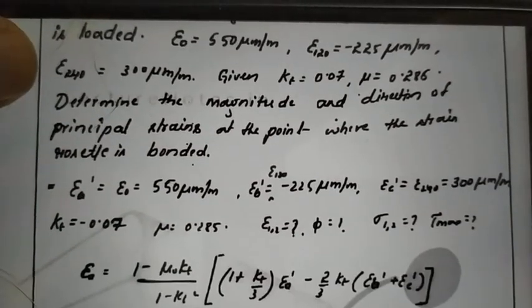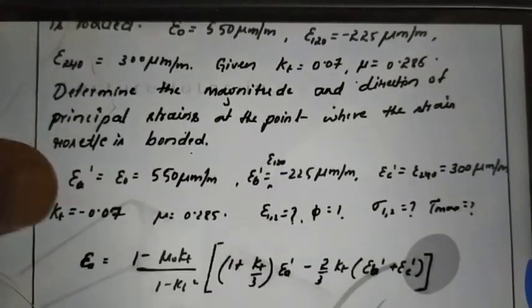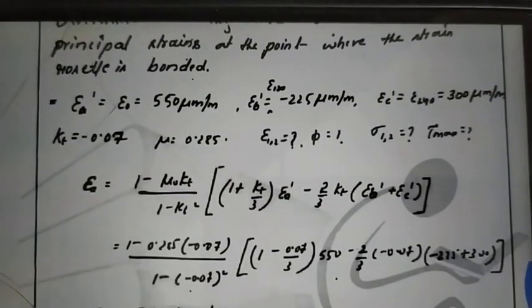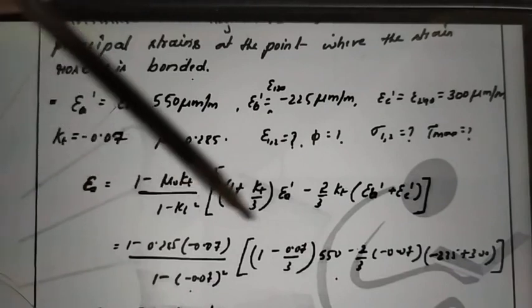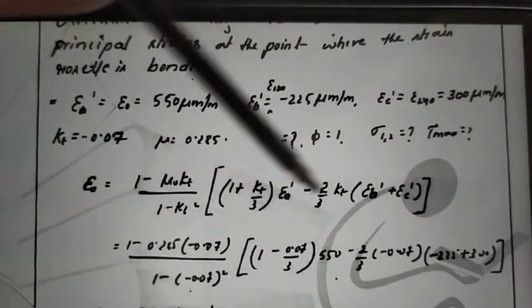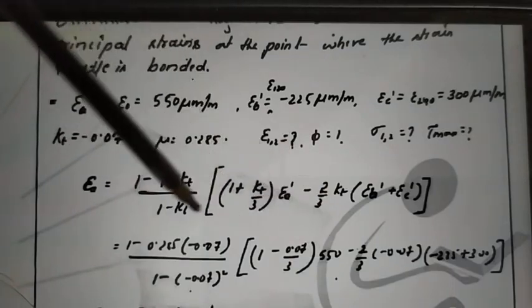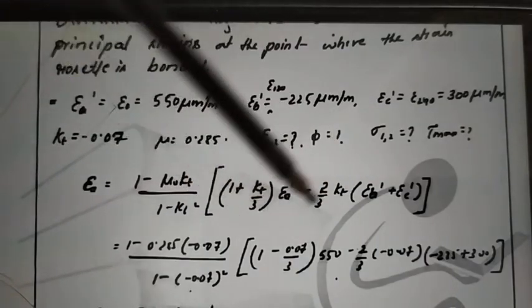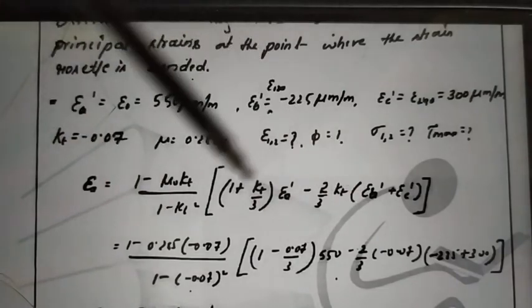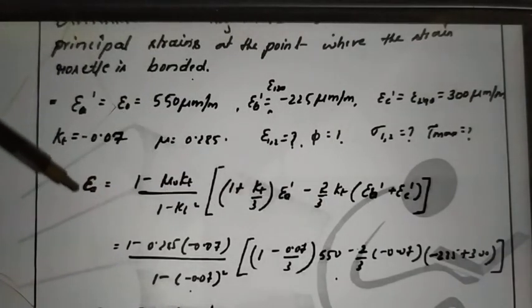Okay, so like that you have to calculate, in a similar way. This is the transverse sensitivity correction value. So here is the same equation. I have given the notes for how this equation is obtained. This equation should be remembered to get the corrected strains.